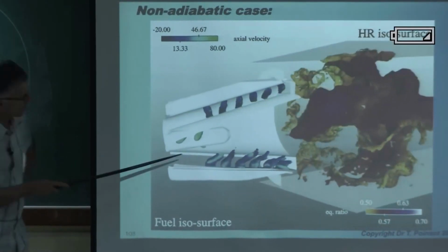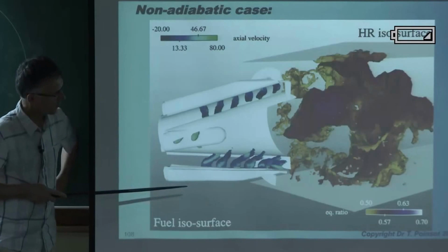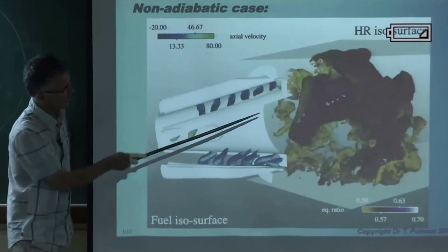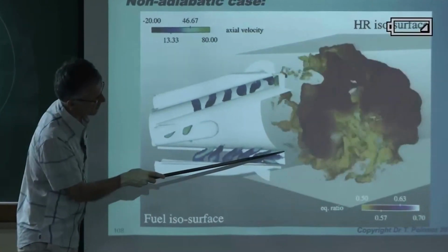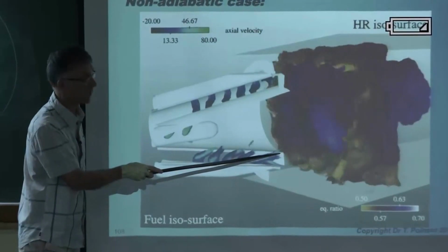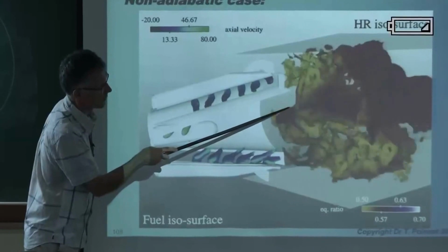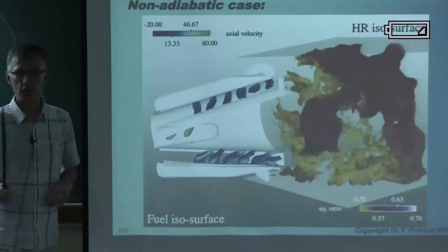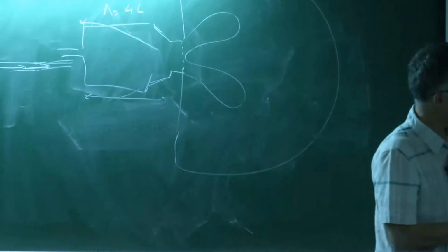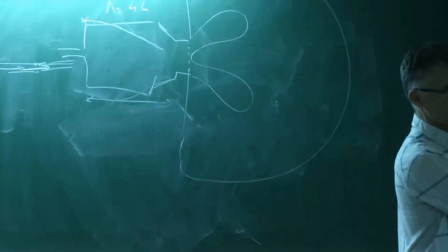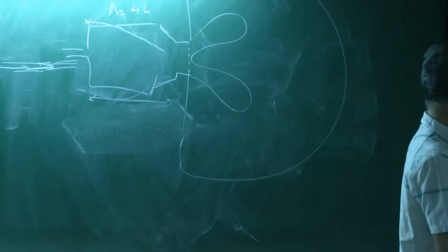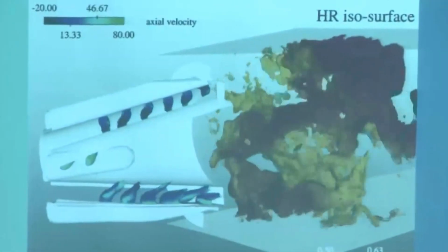So now you see the jets of methane, and you see the reaction rate, and you see now the flame is lifted here. It's not touching this point. It cannot, because this point is too cold. So the flame is still stabilized by the recirculating zone, but then that's also a question which was asked yesterday. That has become a V flame, while before it was an M flame, excuse me.